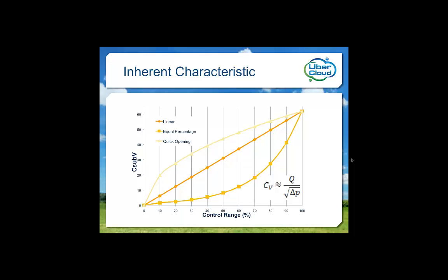The relationship between restriction and control position describes the valve's range of control. The system designer selects a characteristic for the valve based on the projected requirements. The designer can then input the applicable valve ratings in the control algorithm to permit rapid overdamped response in order to maintain system stability during input parameter changes and other disturbances.